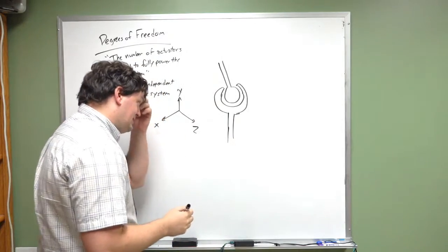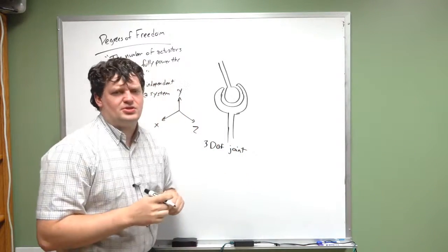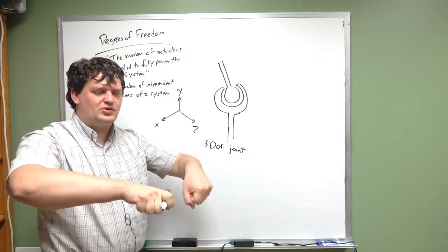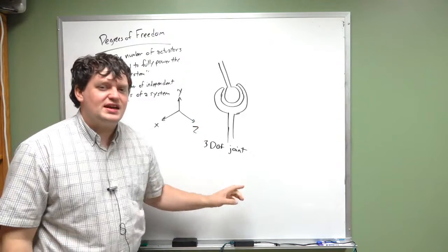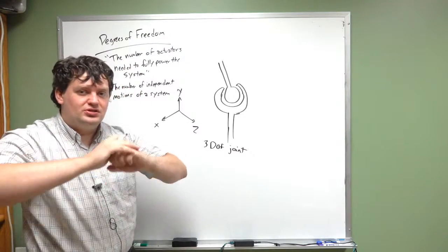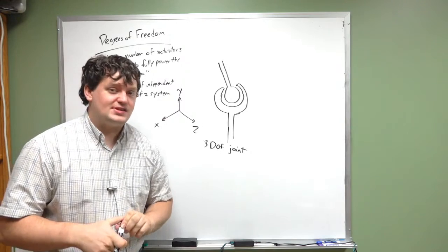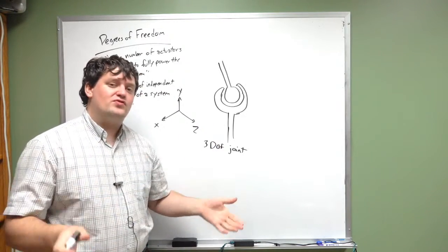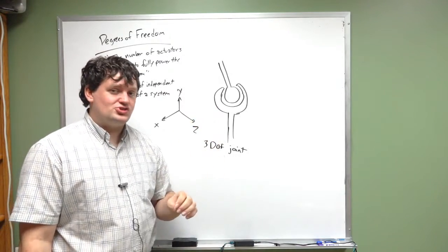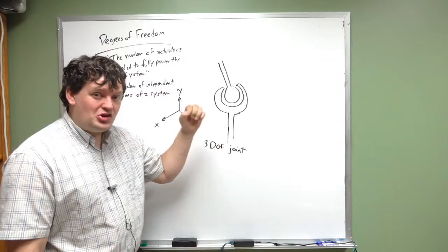What this ball joint represents is a 3 degree of freedom joint. This is a pretty common 3 degree of freedom joint. Ball joints end up reducing a lot of stress on components because you may have stress from components flexing in and out. And as we said, in a revolute joint that creates a boundary condition where it has to resist that rotation motion. If there's just a little bit of flexure, that joint has to try to carry that flexure, and that can cause a lot of stresses if it's not designed to carry it. Out of plane movements for linkages can strain joints substantially because it's causing loading in directions that those components were not intended to be loaded in. This ball joint is intended to be loaded in all directions.